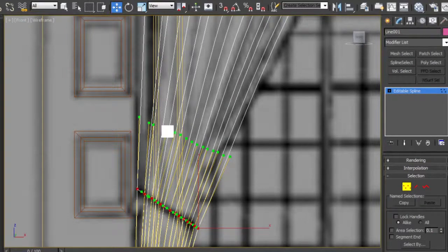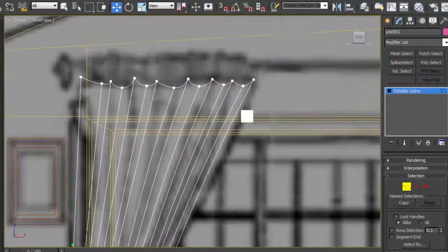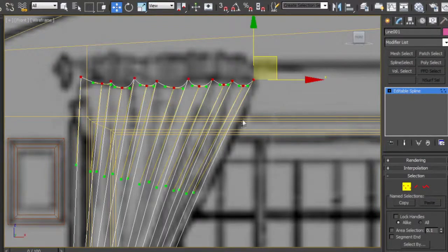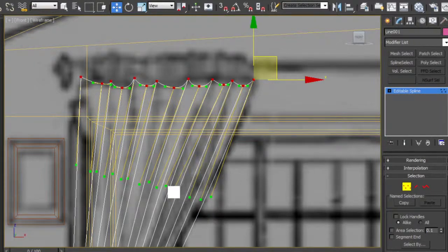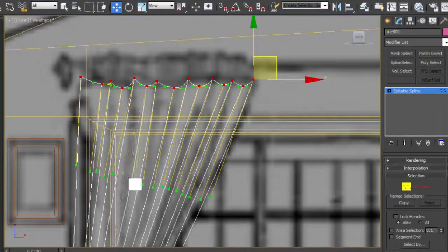In Max 2013 and earlier, to change the gizmo to be selectable and non-selectable, it's called disabling the gizmo. This is the letter X on the keyboard. Evidently for Max 2014 and after, that is Shift Control X, because X is now a search function.